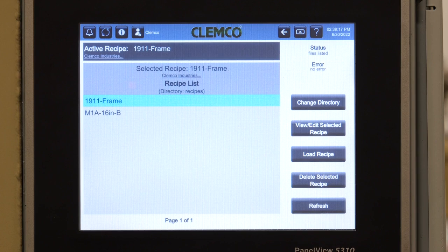There is an eventual limit, but it could be greater than 500. There are programming limitations as to how many we pre-set up for the programming, but the SD card can hold many Excel files. We just have to be told up front, if the customer's planning to use 250 recipes, we need a program for that. It may require a larger memory PLC to do all that logic.